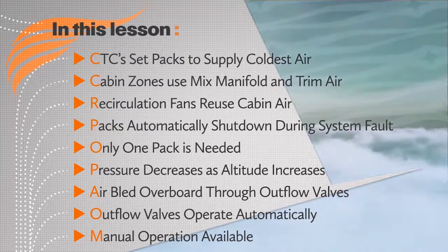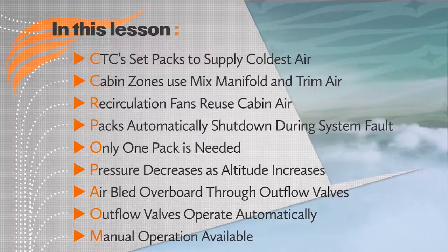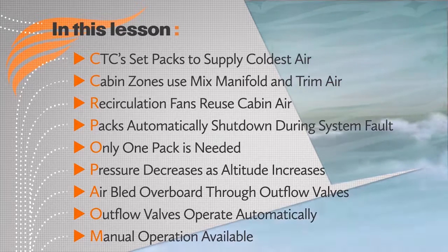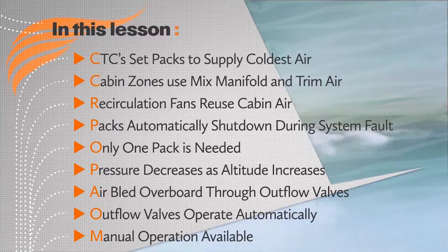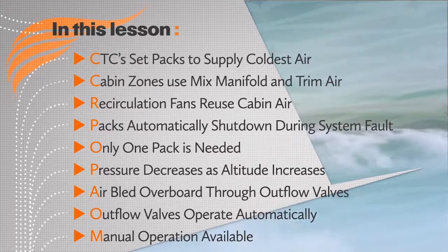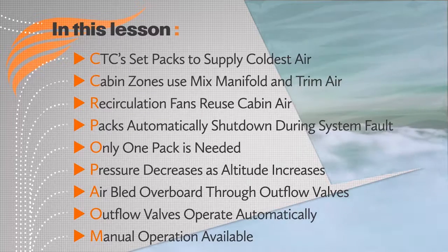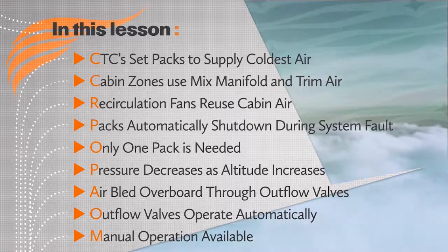Remember, drive the outflow valve to closed if you need more air in the cabin. This will increase cabin air pressure, therefore reduce cabin altitude. Vice versa when you drive the outflow valve to open.